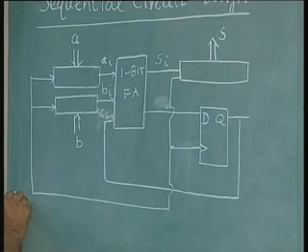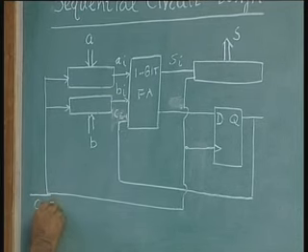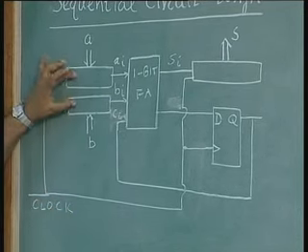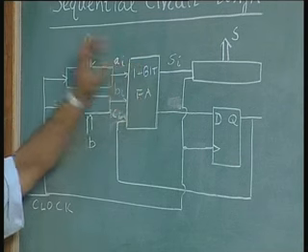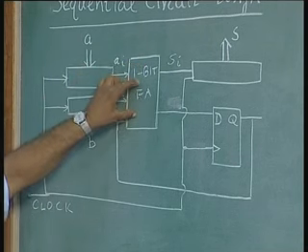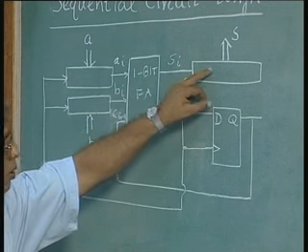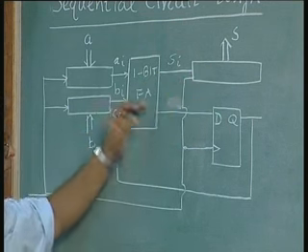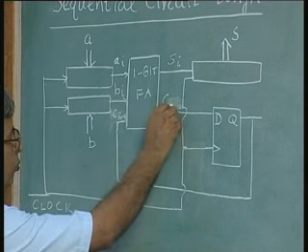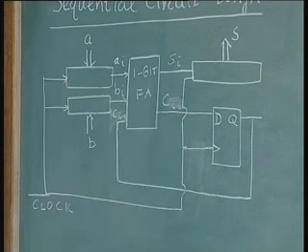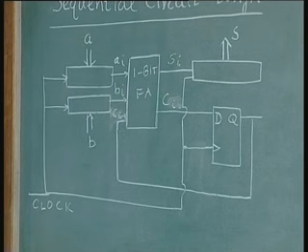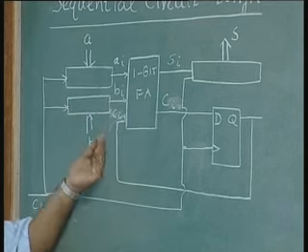So, this is one clock which shifts bit A into the full adder, bit B into the full adder, shifts Si to the sum register, and stores the carry value to be used as the Ci minus 1 for the next bit addition. This is a sequential circuit design, the concept of sequential circuit.